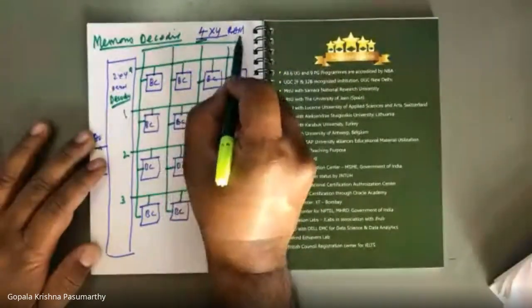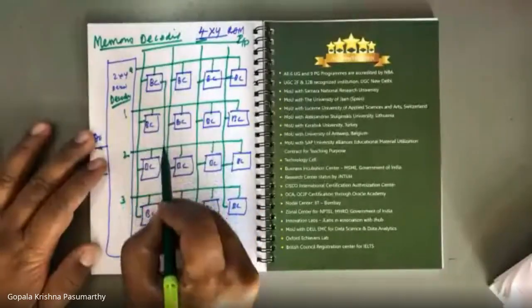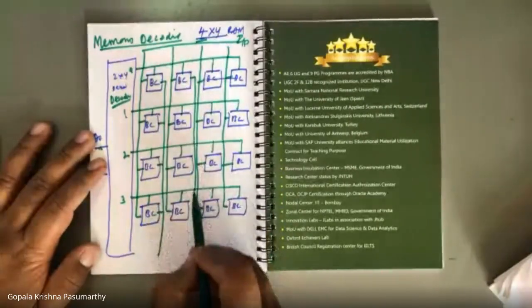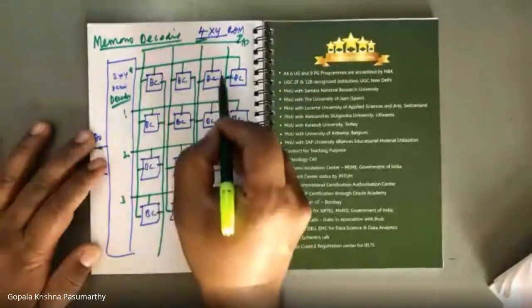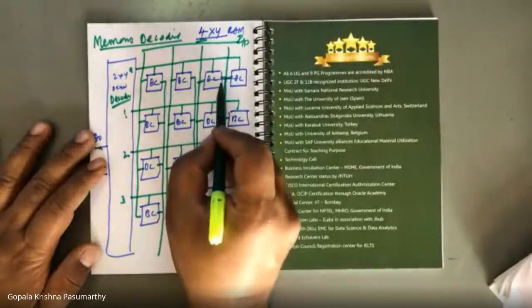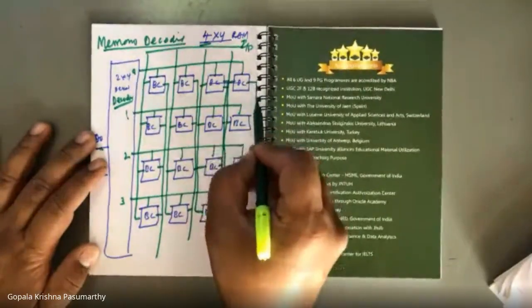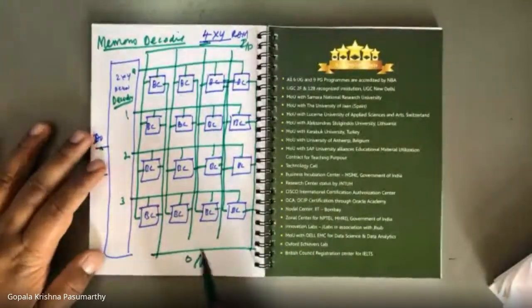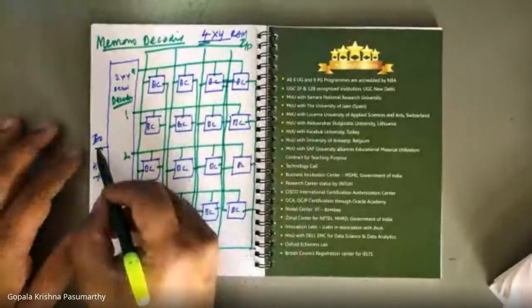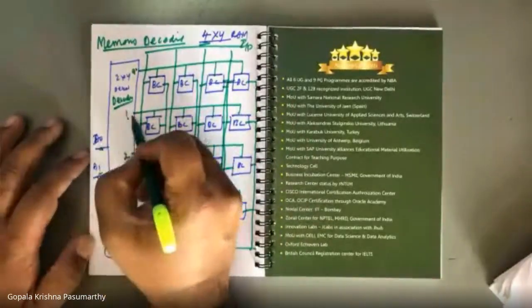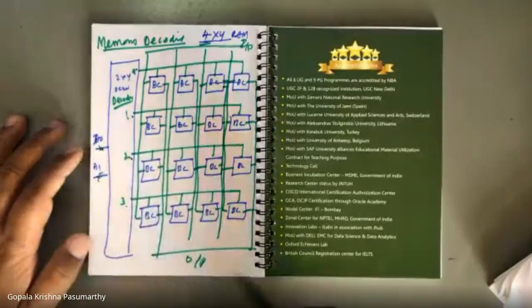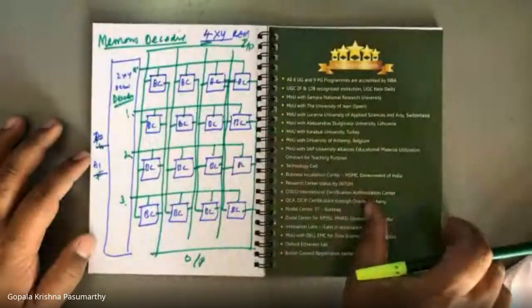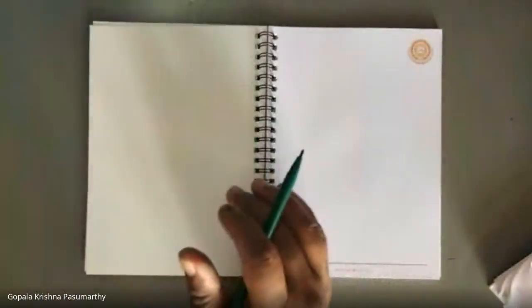See, these are all called input lines. In the same way, we will have output lines. Every binary cell gives you an output, as I told you earlier in the concept. These are called outputs. So inputs, outputs, select. If this is 0 0, the 0th line will be active. 0 1, the first line. 1 0, the second line. 1 1, the third line. So depending upon the given address, a specific word will be selected. That is what we have to understand. This is called memory decoding.